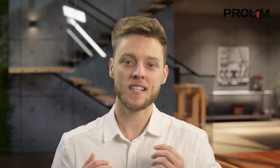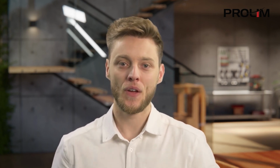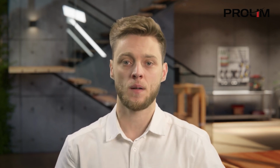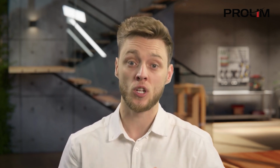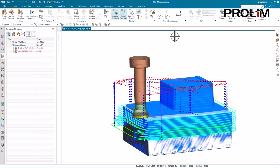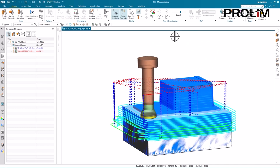Next, we'll create a rest milling operation for the mold core. The rest milling operation will remove any residual material left after the adaptive roughing operation. We're going to choose a longer end mill tool with a smaller diameter for this operation. With our ranges specified, notice the milling operation in action.